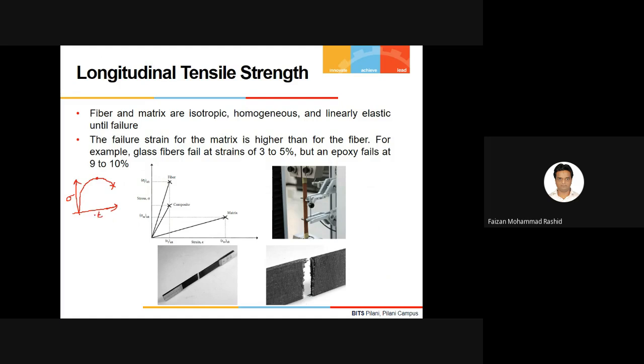But for composite material, where both fiber and matrix are brittle, you have glass fiber, carbon fiber, these are brittle materials. So in that case, you will have data points up to here, and you don't have any UTS. In fact, up to here you have yield stress, so UTS will shift here only. Whatever point you can say is the yield is called the UTS also for brittle material.